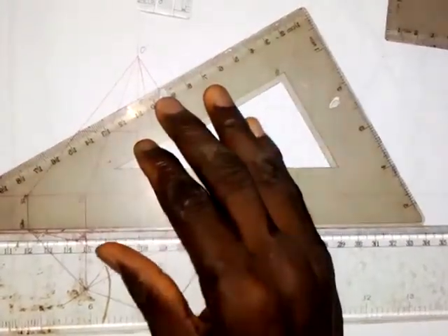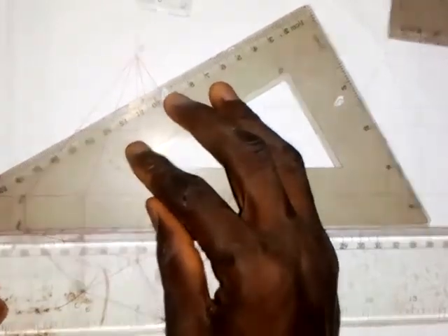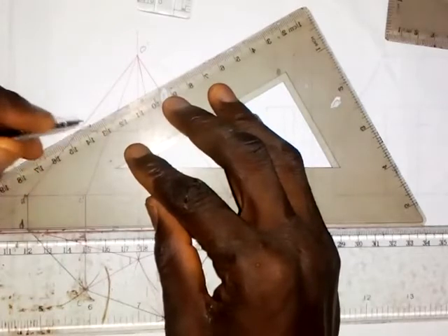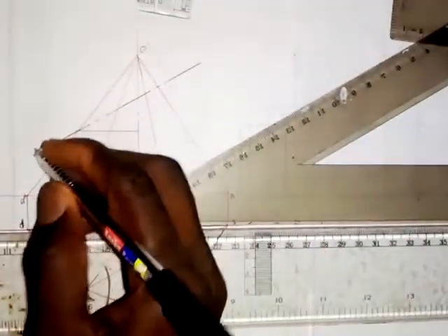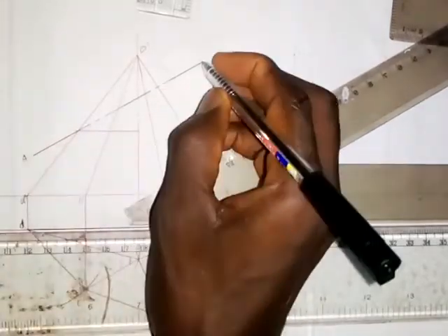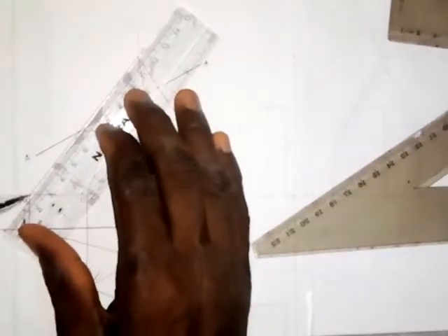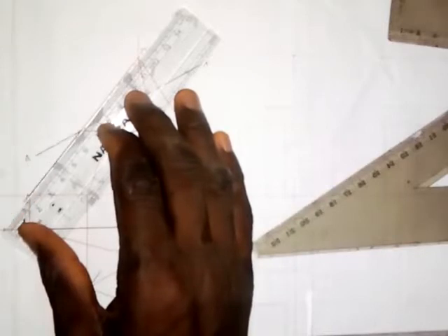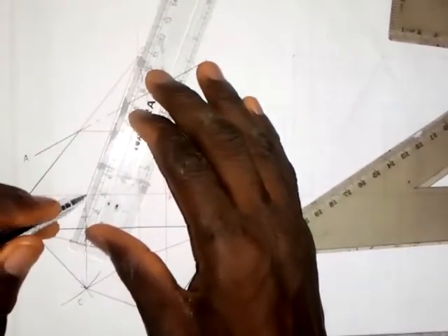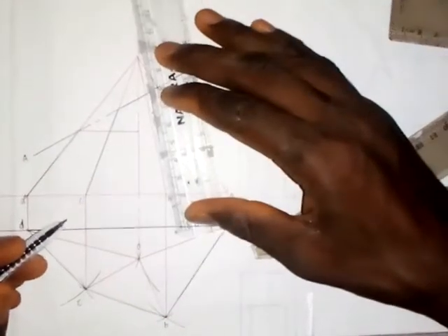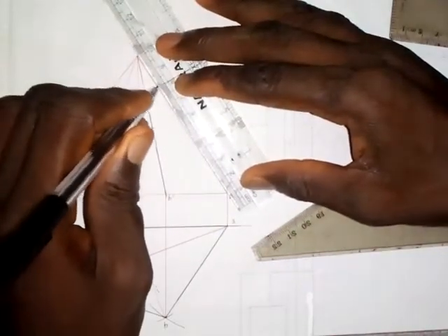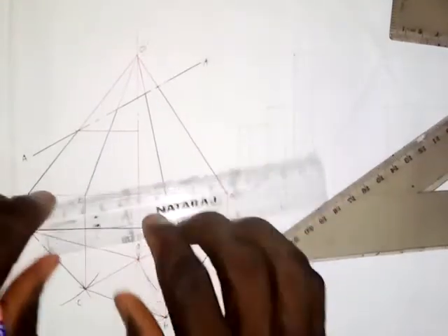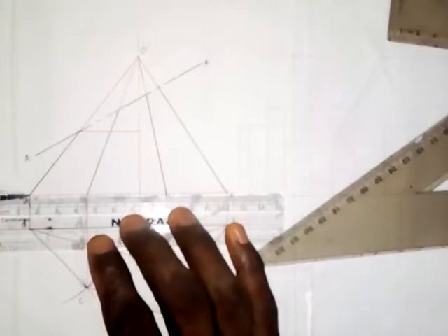All right, so I will draw the cutting plane now, with my 30-degree set square. So this is the cutting plane AA. Now this part is cut off. The remaining parts, from here to here, make it with a thick line. Make this a thick line, make this also a thick line, and this from here to here. The base, I will also make a thick line.